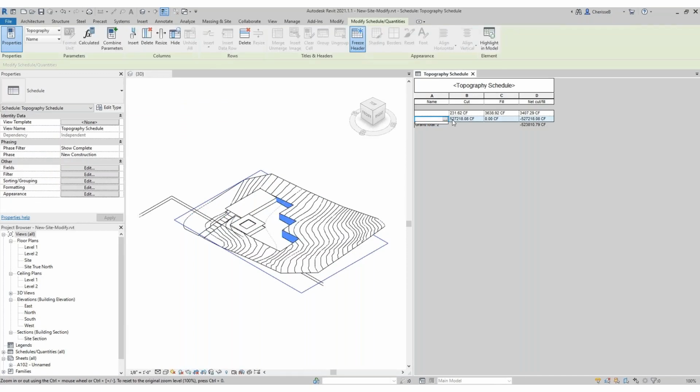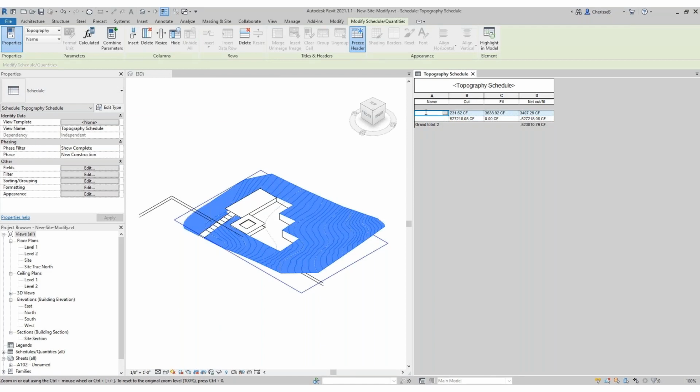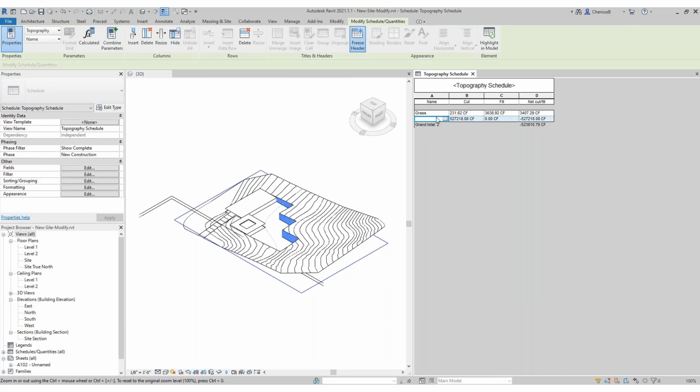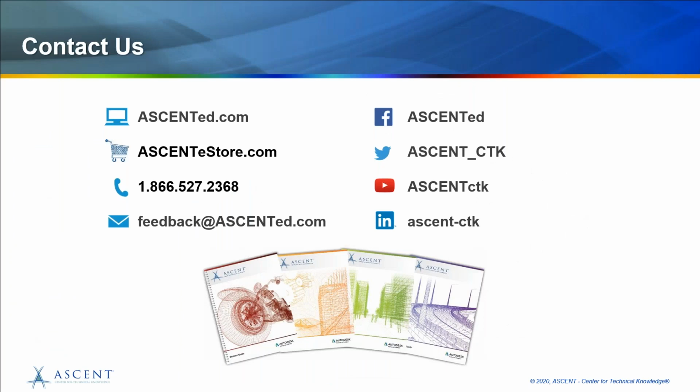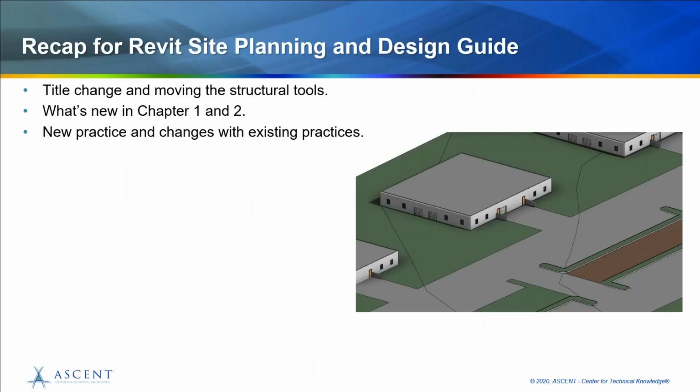I think this would be great to show people because as you select on the schedule rows, you can show them that that's the grass area, I can label it. When you select on that, that's highlighting the building pad, so I can specify it in the schedule. Because I don't have you name the actual surfaces through this process. So I think that would be great to show how you can see that interactive with Revit. Woo! I just double clicked right through that.